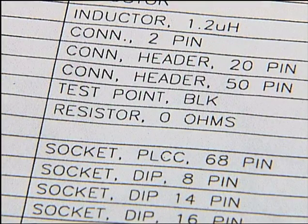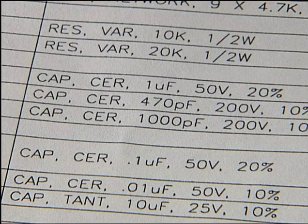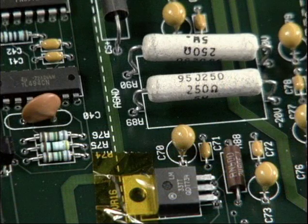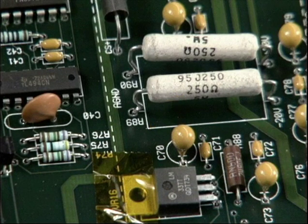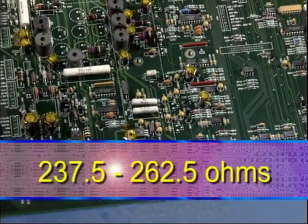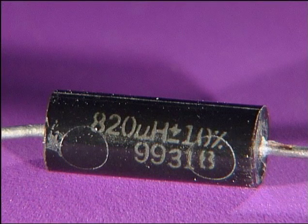Another method of identifying some components is by their value. A value is a numerical quantity given to the component. This value is usually assigned a plus and minus tolerance, which is the variation allowed from that value. For example, resistor values are units of resistance measured in ohms. If a 250 ohm resistor has a 5% tolerance, its acceptable operating range would be 237.5 to 262.5 ohms. We'll talk more about specific component values and tolerances later in this video.